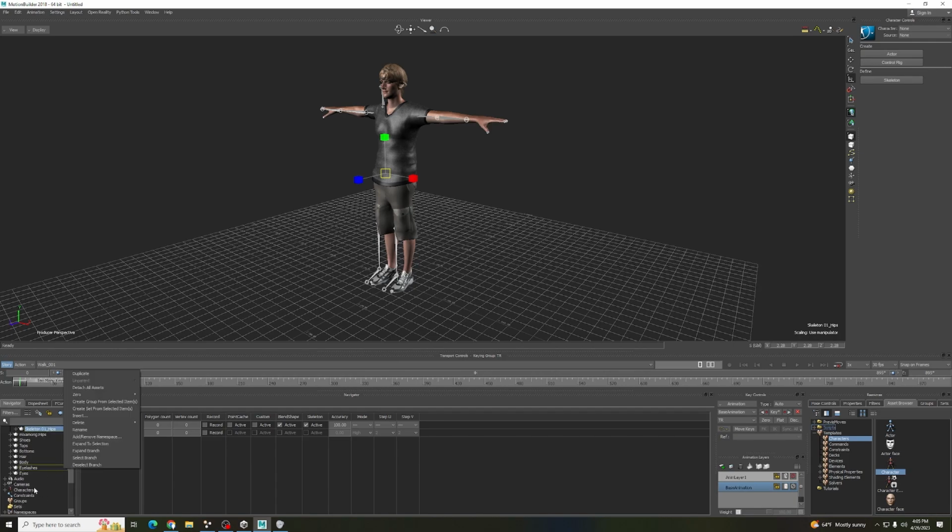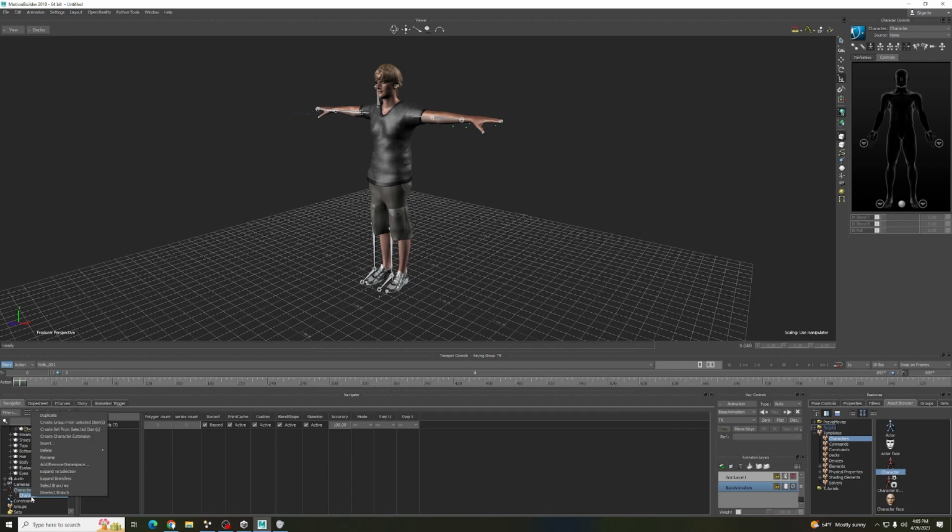You can rename this character by going to the Characters tab, expanding it, finding the character, and renaming it. We're going to call this Motion Source. And now, we're going to do the same to Remy. In this case, we don't need to set everything to 0, as it's already correctly set. Make sure you're on the hips, click and drag, then characterize.